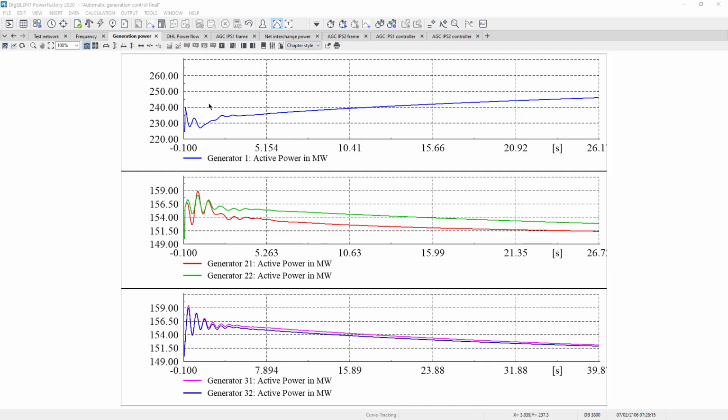Okay, you can see here, initially we have a sudden change in the active power of some generators. Remember, that is related with the location inside the power system, the relative location between generation and the disturbance, and also the synchronizing coefficients. I will not go there with that kind of explanation, but that is the natural response, the natural network inertia response of the system.